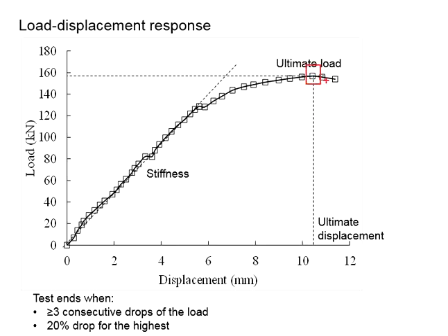Once you observe the plot has peaked, then you suspect that the specimen may have failed. To confirm that, you can proceed with the loading and observe if the specimen can gain further strength. If the following readings can give you higher strength than the previous one, that means the beam can withstand more strength and the ultimate load has not yet been achieved. But if the following plots here cannot go higher than the previous one, for at least 3 consecutive drops, it is likely that the ultimate capacity has been achieved.